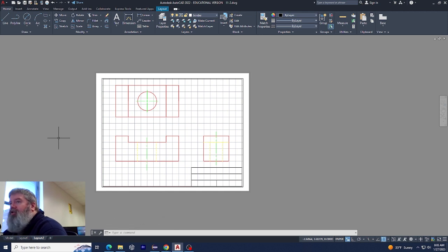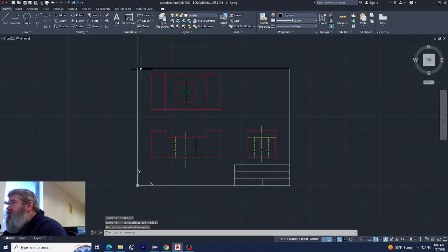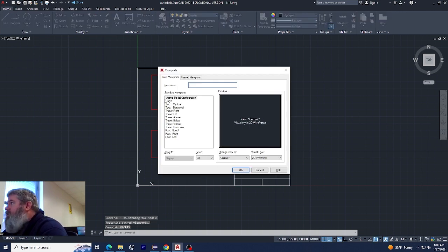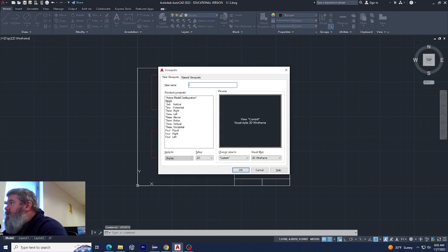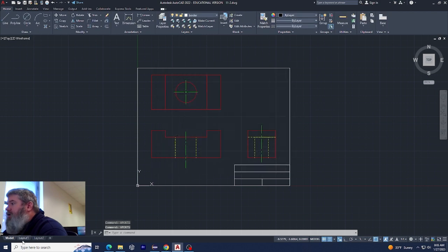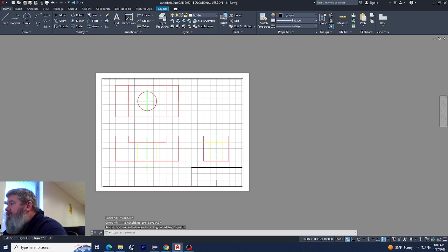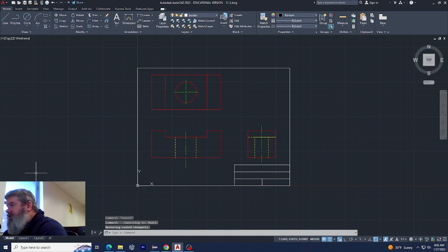Both paper space viewports and model space viewports are created using vports. So you can also make one in here. This could be a viewport. So you could do vports. You could do a single vport, and apply to display. So that means it's going to apply to this right here. And since we already have it in there, it's going to be in the right place right there. But I don't ever do viewports in the model space. I just do them in the paper space because it's really made for your layout and for what it's going to look like in the end.